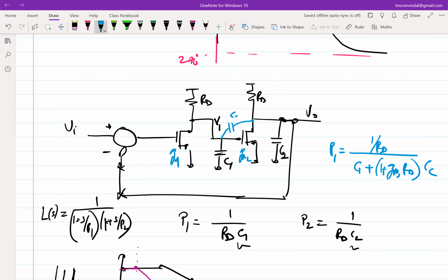Again, the question is, in the previous case, when I had put the capacitance between this node and ground, let's say the CC required happened to be 10 picofarad. So now I'm saying I'm not doing this. I'm doing Miller. What will be the effective CC required? More than 10 or less than 10? Less than 10, because that CC seems to be amplified by the Miller effect.